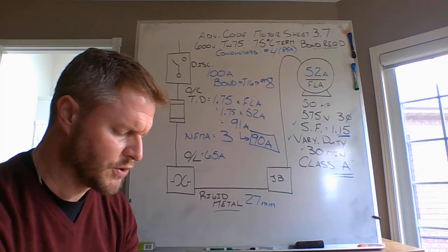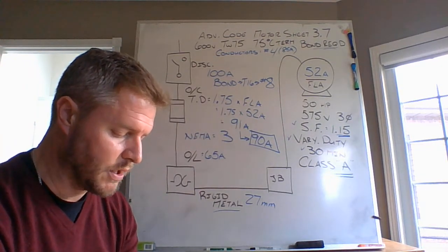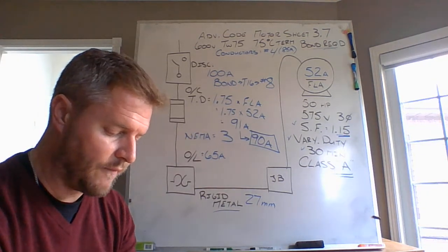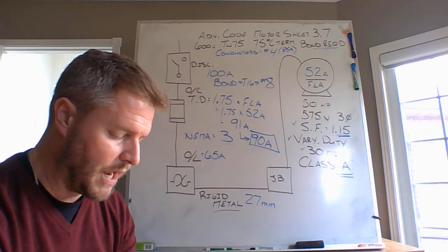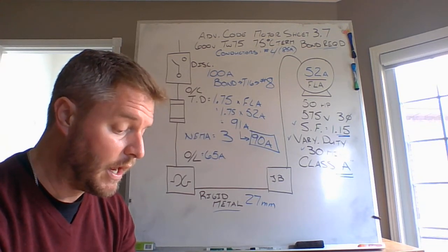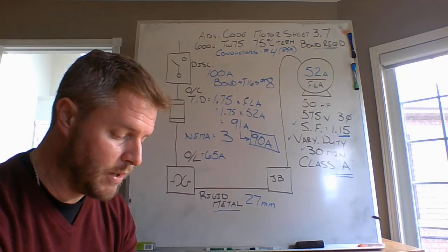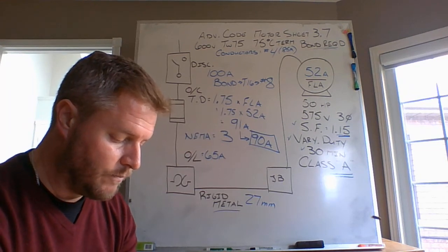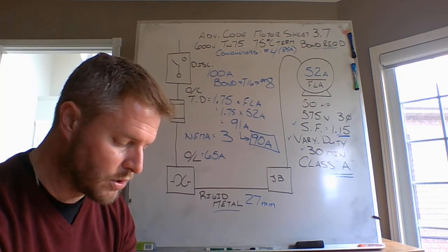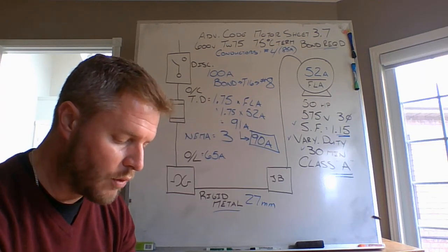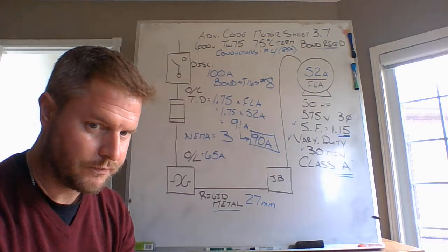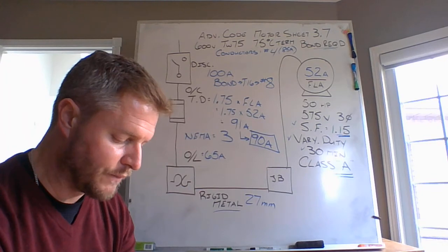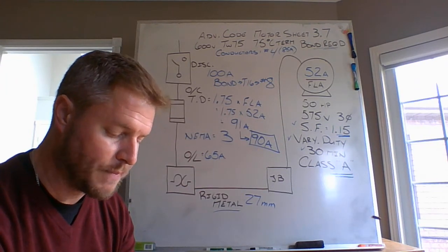28-104 subrule 3 says where table 37 requires insulation temperature ratings in excess of 75 degrees Celsius, the motor supply insulated conductors shall (a) be not less than 1.2 meters long and terminate in a location not less than 600 millimeters from any part of the motor or motors rated less than 100 horsepower. And then part 2 to that rule says 1.2 meters from any part of the motor for motors rated 100 horsepower or larger.